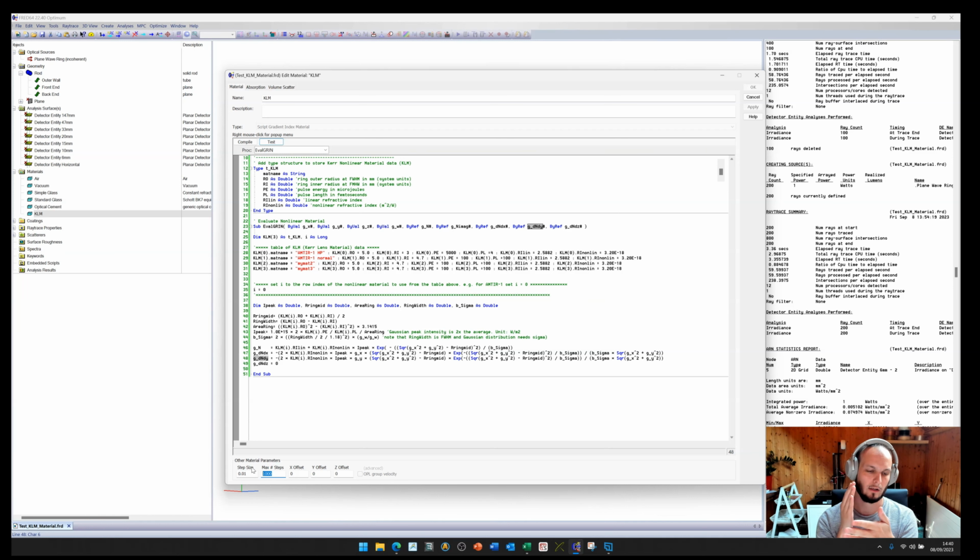You want the material to have a different index at different distances from the middle, and this is the resolution. The step size will be 0.01 millimeters, because millimeters are my system units, and for the steps I've chosen 1000 steps. I guess if you choose more steps, the calculation will just take longer.